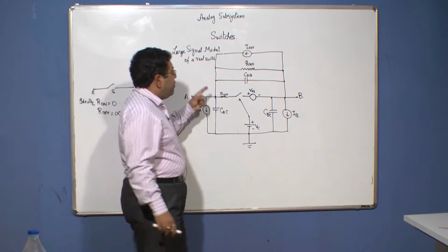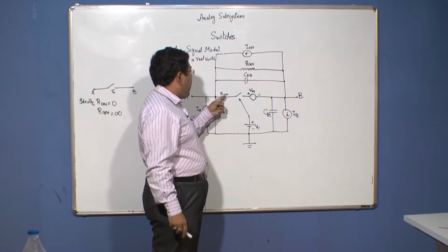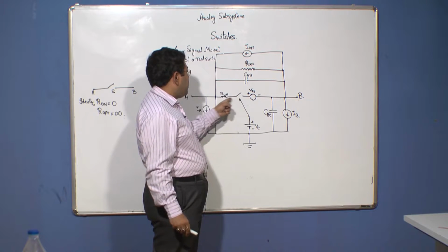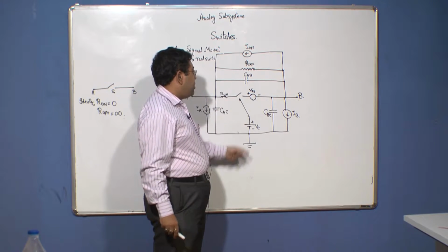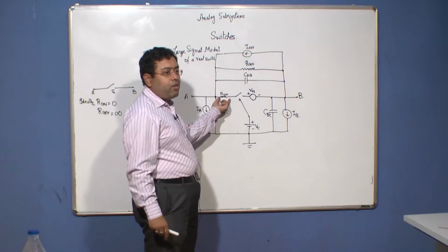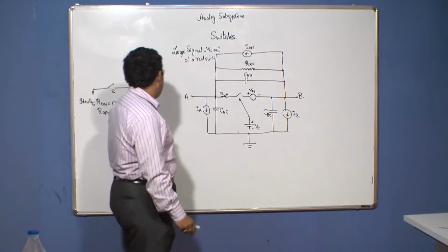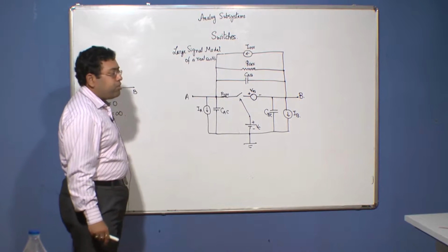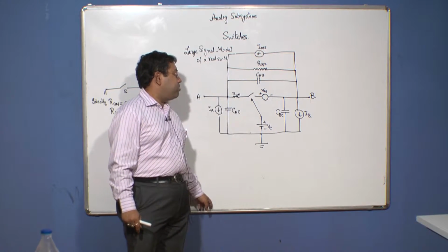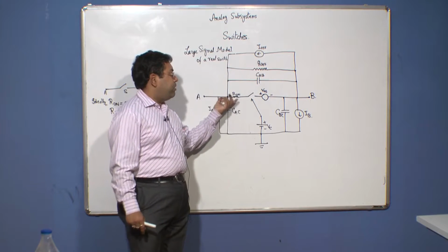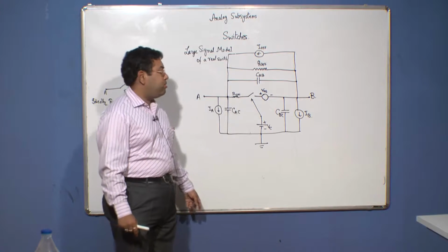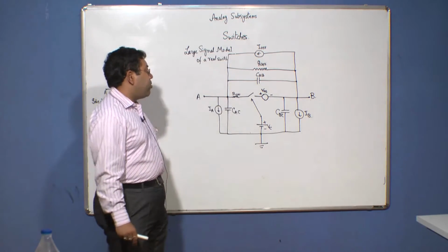In this model, you can see that when you close the switch, you do not have a perfect short circuit between the terminals, but there is a small voltage drop across a resistance R on. This accounts for the small voltage drop across the switch when you apply a potential between its ends and close the switch. So, we do not really see the potential at the two end terminals equal, but there is a small drop across the switch which is modeled by this resistance R on.